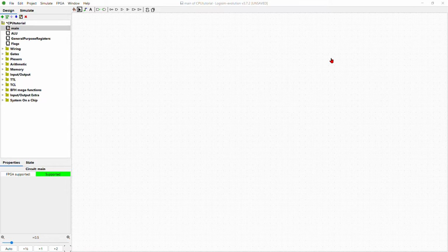So let's start off by just talking about it a bit. The main circuit has an internal address bus, an external address bus, and internal and external data buses also. The purpose of these is to help abstract the flow of data. So if you want to get data from the internal part of things, that's the registers, the counters, all that, to let's say your RAM, which is external, you'd have a way of doing things. It helps to make things easier and also easier to debug.